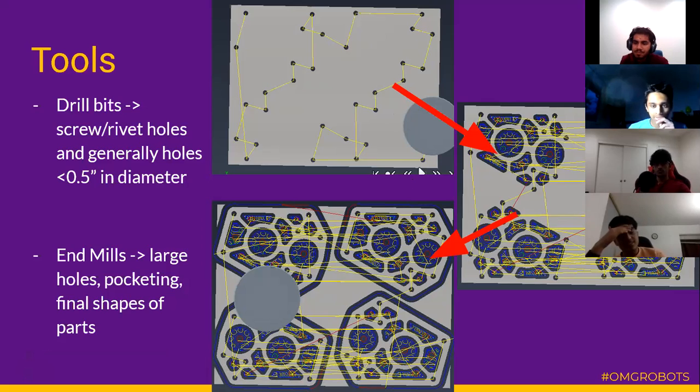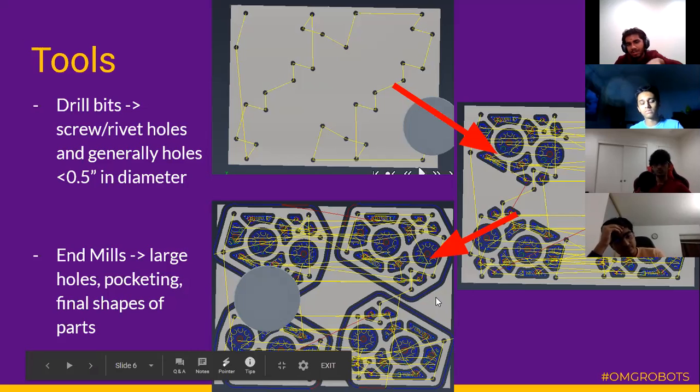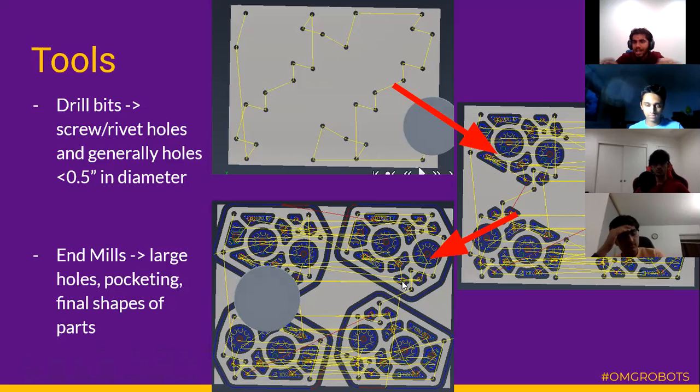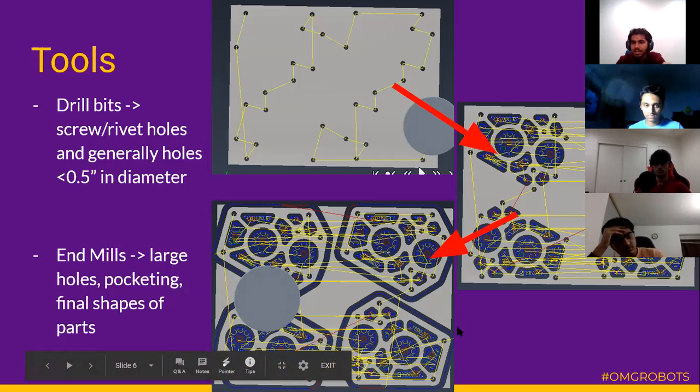If you went in reverse, there's nothing holding the part you're cutting in. Yes, that's exactly the reason, right? If you imagine if I only did the outline of this gearbox plate first, there would be nothing else on this plate and it's already been detached from the rest of this rectangular aluminum sheet. And so it would be free to go anywhere it wants to, right?